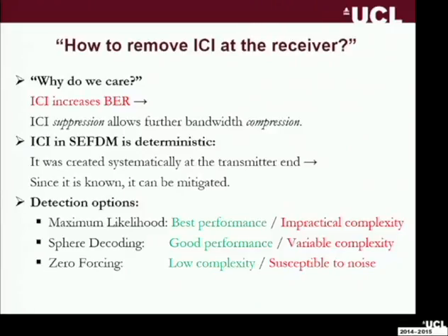What happens if you've got 4-QAM, for example, with 32 subcarriers? So you've got 4 to the power of 32, or 2 to the power of 64, possible combinations. I'm talking about trillions of combinations, probably not doable, at least not in real time. You may wait a few years to get your symbols back, but you probably wouldn't get them in real time. So we thought, okay, maximum likelihood is not possible. What's the simplest solution? Well, the simplest solution is zero forcing.